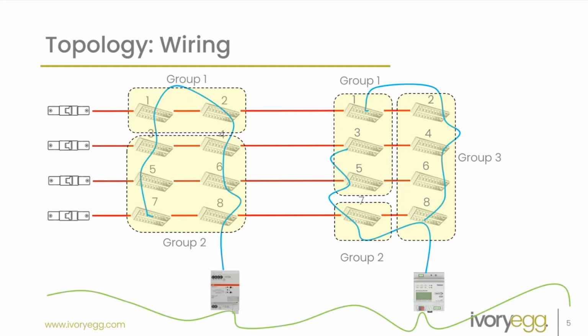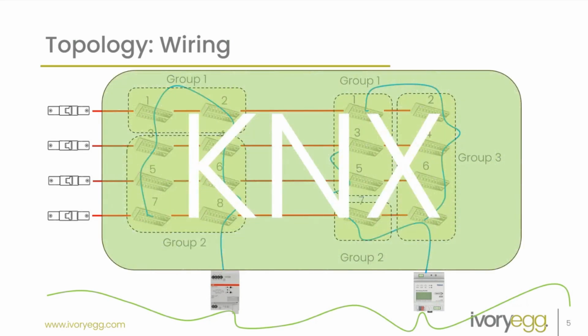And Dali will support up to 16 groups. So of those 64 fittings, you can have 16 groups. Okay. Now, the beauty of using KNX with Dali is if we had 2 Dali gateways or 2 universes, and we had to have switching of a commonality between those 2 universes, we can always stick the Dali groups 1, 2, and 1, 2, 3 from each different gateway into the same KNX group address. And then from the customer's perspective, it's all one group or one switching group.